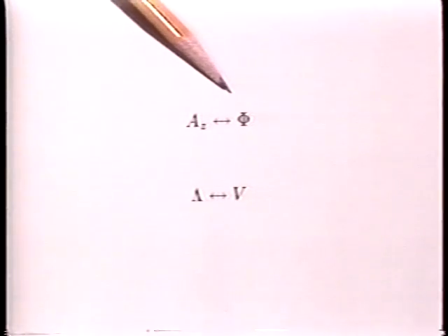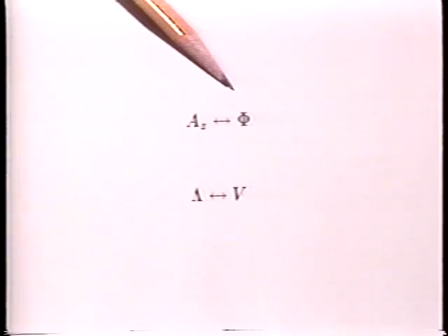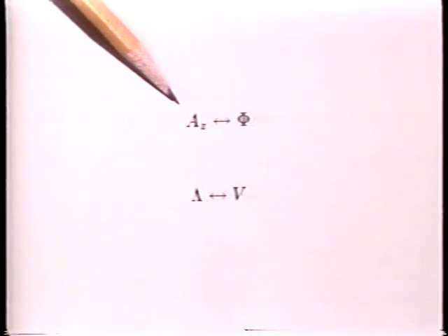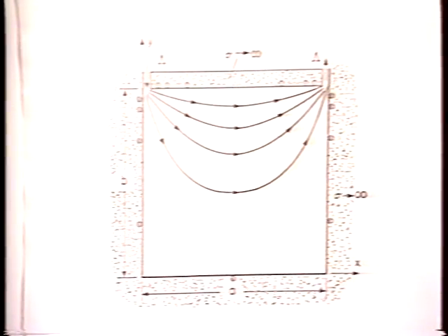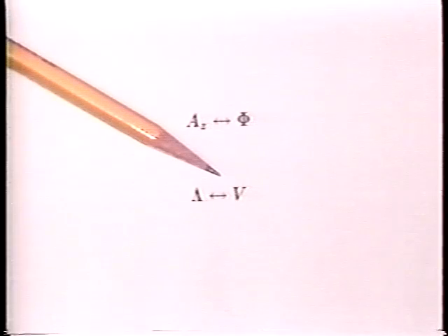If you're familiar with using a scalar potential to represent an irrotational electric field, the role played by the scalar potential is being played here by the vector potential. Lambda is the flux per unit length passing through the gaps at the ends of the top electrode. In the electroquasi-static analog, this flux is analogous to the voltage between the upper electrode and the wall.